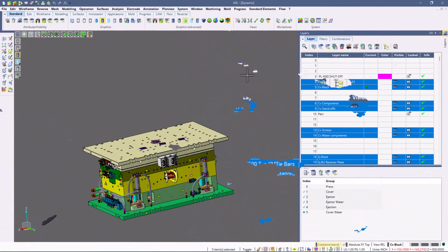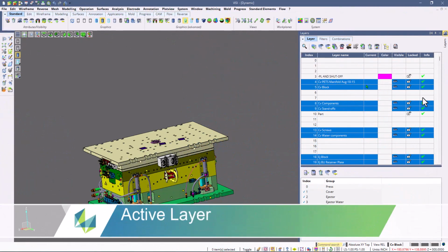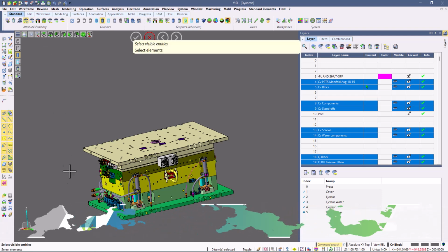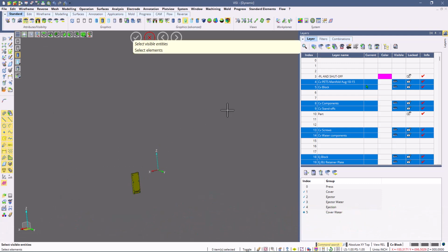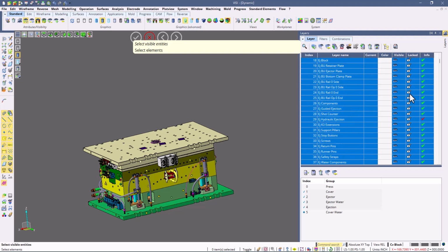Now we'll talk about active layers. Active layers represents that there's data in this layer. These layer checkboxes show up as green if everything is visible. But if we're using our attributes of visibility eyeballs, the checkboxes will all of a sudden turn red. So now you can see the green checkboxes mean everything is visible, red checkboxes mean there's data there, but some of it might not be visible.